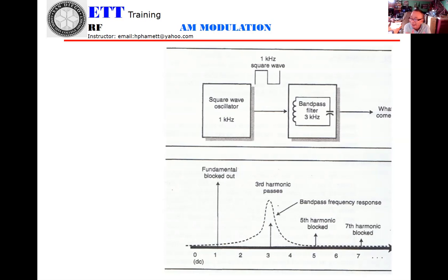Okay? Band pass, you have an upper frequency and a lower frequency. Any signal with a frequency less than the lower, stop. Higher than the upper, stop. They allow only signals between the lower cutoff and the higher cutoff to pass through. Okay?